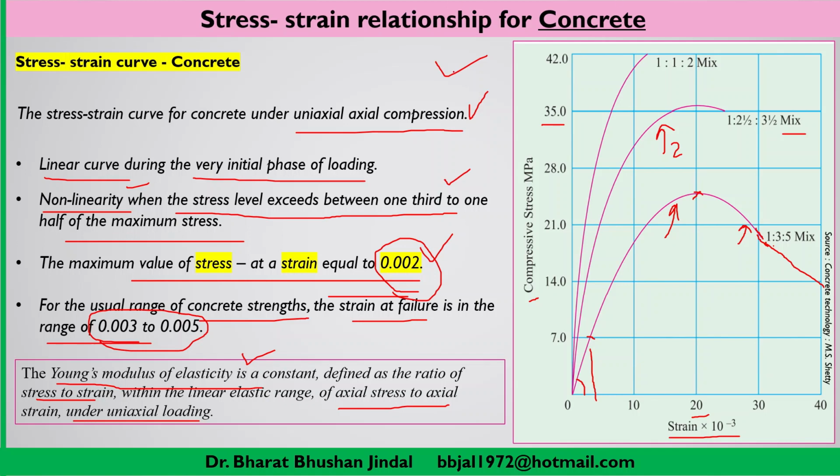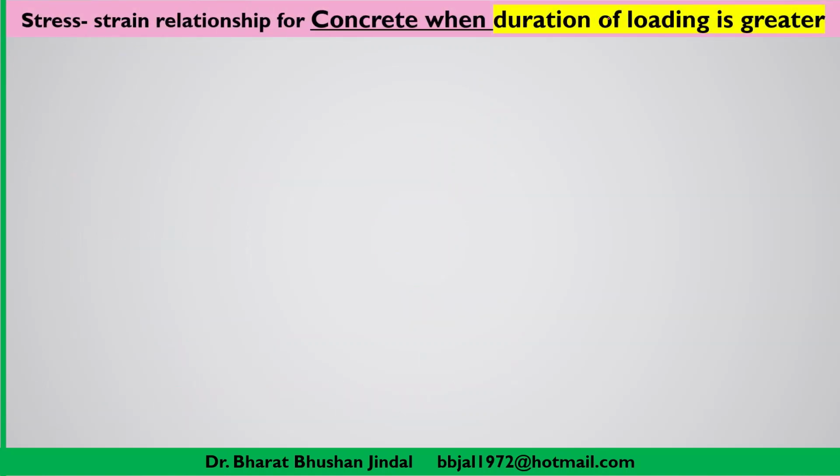But in general, when concrete is used in construction, that means in RCC structures, the structure will be subjected to loading not only for 10 minutes but maybe for 1 year, 2 years, like that. So now we have to understand the stress strain relationship for concrete when the duration of loading is greater. Whether the behavior of the concrete will change, or whether there is variation in the stress strain relationship, we will be able to understand now.